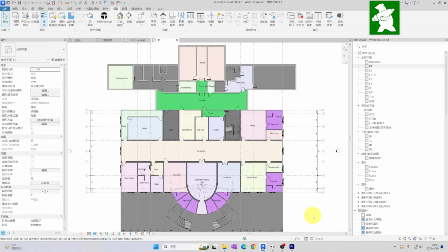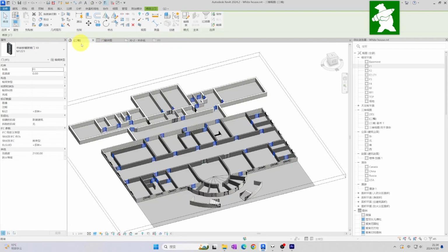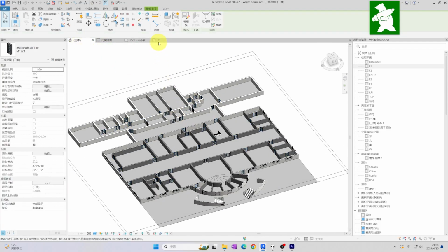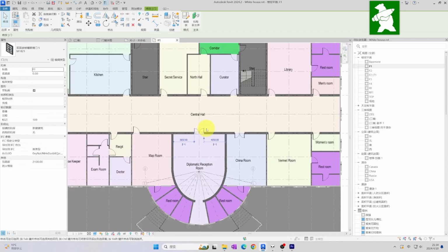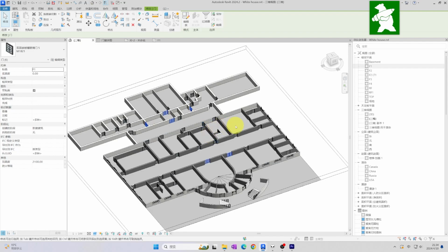As for the inner doors, I did not make detailed distinctions because I did not have detailed information. Instead, I used a similar door and placed it according to the floor plan. The legend view will add doors simultaneously, and the door schedule will count the quantities and get parameters like width and height as well.